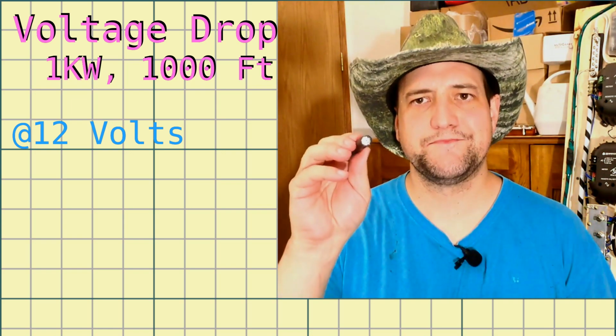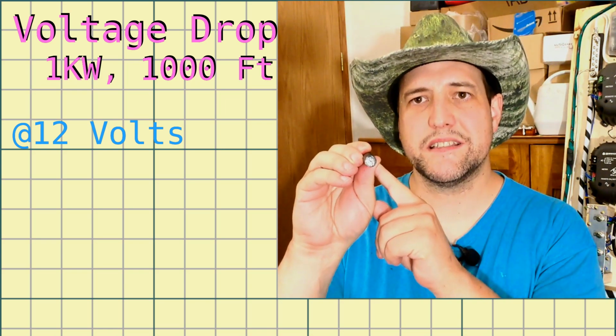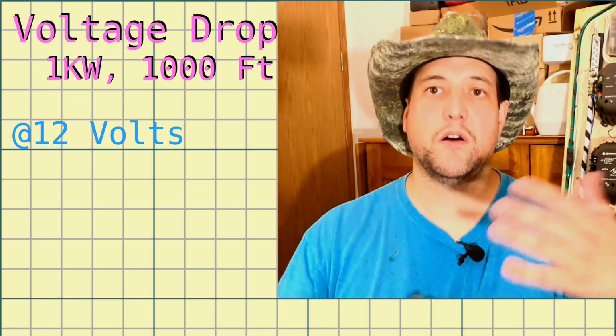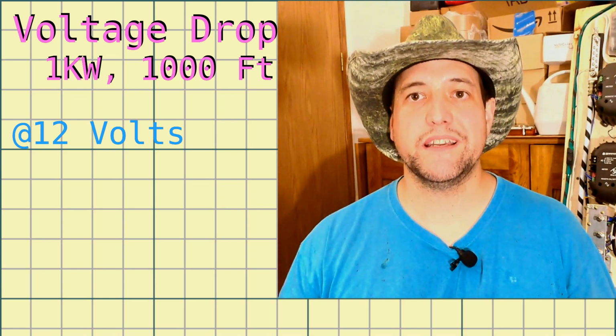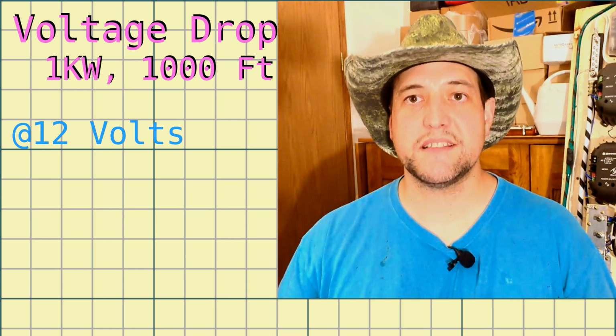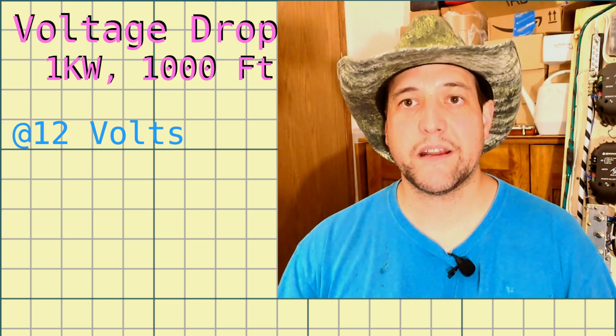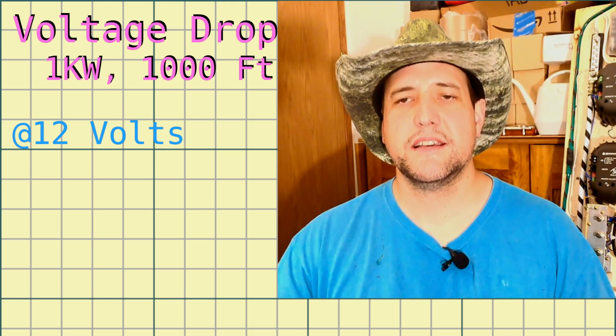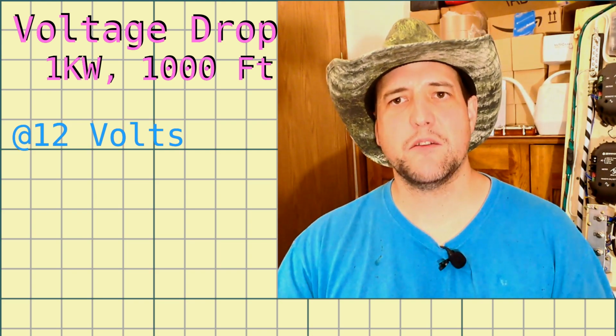Anyways, so if we can't use this, what are we doing here? Well, we need to minimize the losses at the other end. Because if we eat all the energy up along the way, well, that's just not any good. You're going to lose tons and tons of energy the whole way, and you're not going to be able to run the appliance on the other end. Now, I did some calculations, and to minimize the loss, say we're only going to lose 2% of the energy the whole way, we need 1,000 MCM cable.